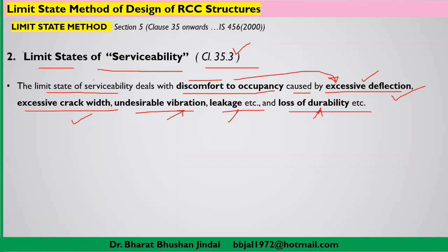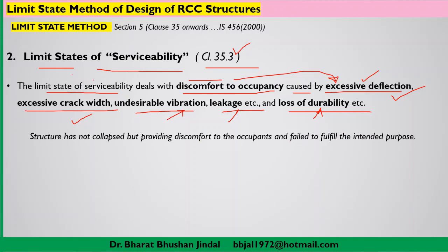All these parameters were not addressed in the working stress method. So that's why it is the limit state of serviceability. Now we can understand here that the structure has not collapsed, but is providing discomfort to the occupants and has failed to fulfill the intended purpose for which it is made.